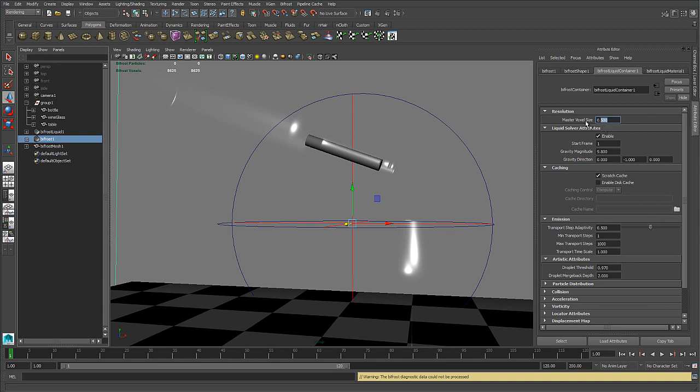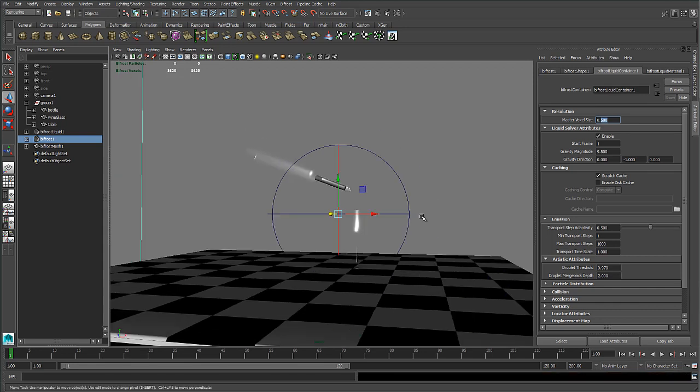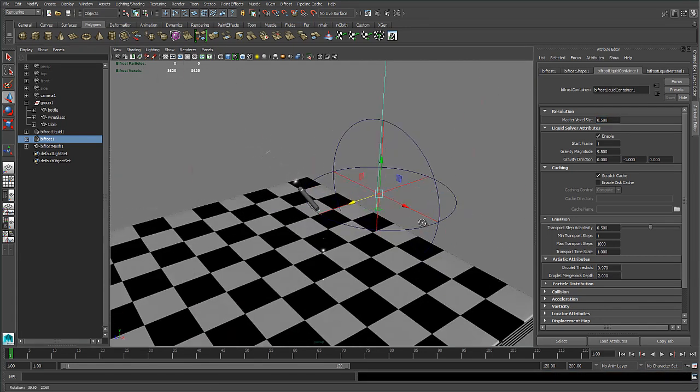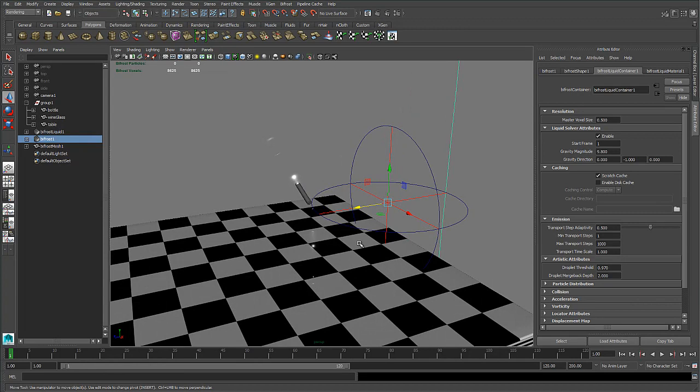What that basically means is that the simulation is going to be based on boxes, not visible, that the particles in the simulation move around inside. At the moment those boxes are 50 centimeters cubed, so they're 50 centimeter cube boxes or voxels, and inside those voxels are the